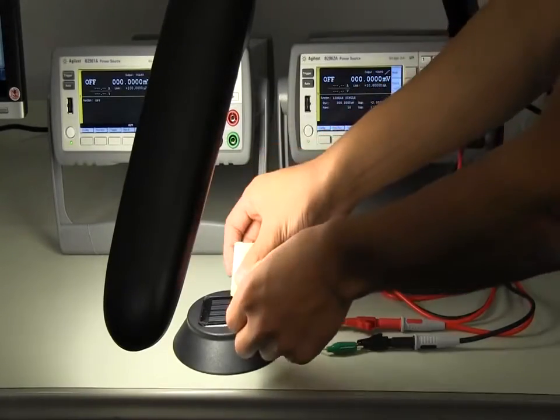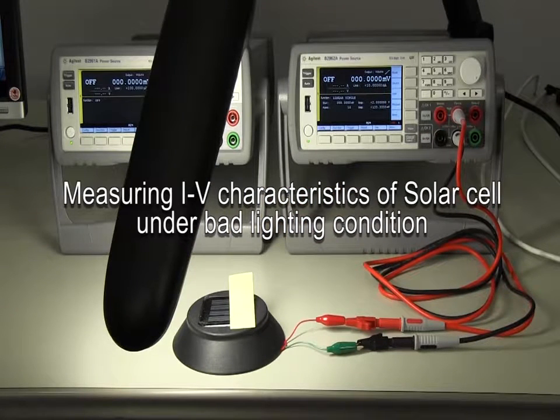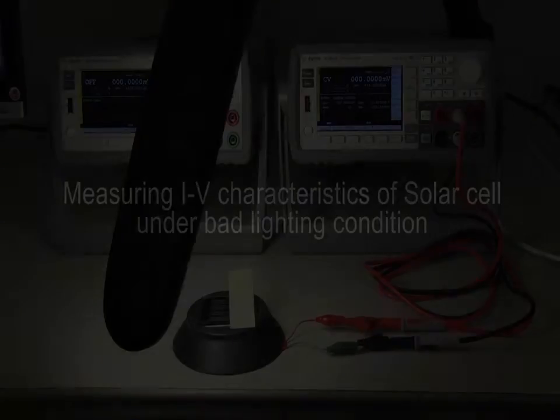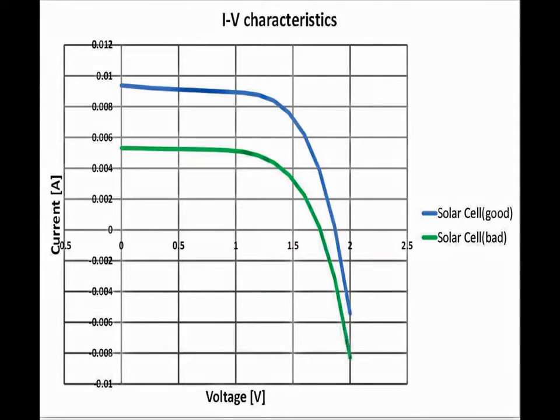Next, I measure the characteristics in bad light condition. This time, I use this paper to make shadow on the cell. There are two IV curves on the graph. Blue and green lines show the IV curves in good and bad conditions, respectively. As you can see from this graph, the voltage in bad condition is lower than that in good condition.